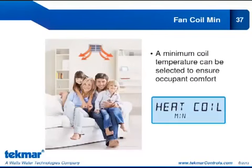Fan coil min is a setting that is also in the 545. So if you're familiar with the 545 thermostat, you're familiar with the fan coil minimum setting. And that is just to set a minimum coil temperature that must be reached before the fan is turned on so that we avoid blowing cool air into a space. Now, obviously for this, you will need a coil sensor in your application.